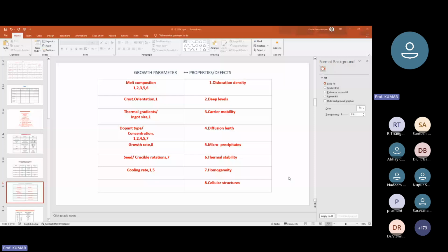You cannot use silica crucibles for RF heating, because RF has to have a kind of coupling, it should receive these frequencies, and silica cannot receive them, so it cannot be used. You can use simple glasses. We all use various glass materials on a day-to-day basis.